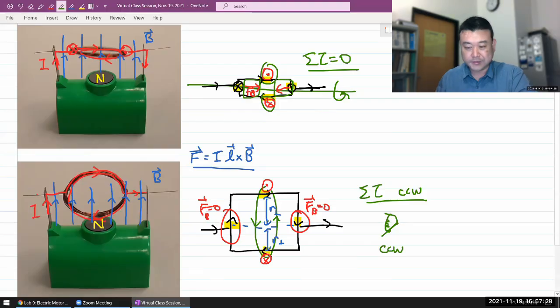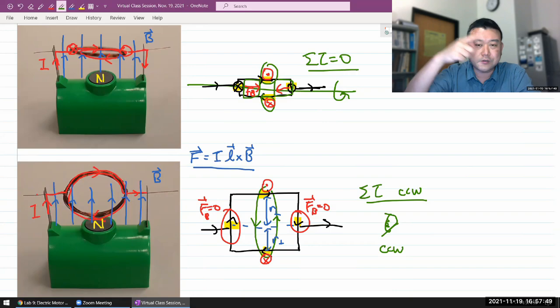For our world's simplest motor, all we have done is introduce a bit of asymmetry so that in one orientation there will be torque, and in the other orientation there won't be torque, but the inertia will carry through. As long as the motor receives enough integrated torque over a full turn, it will continue to run, as you've seen in the demo.